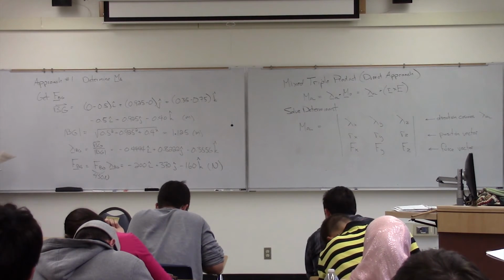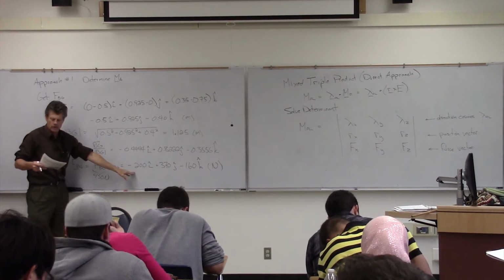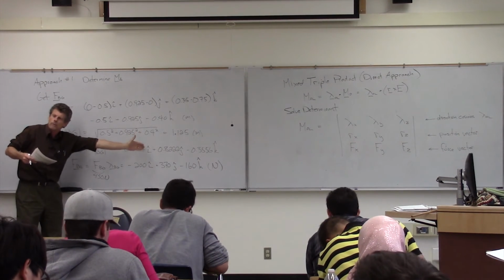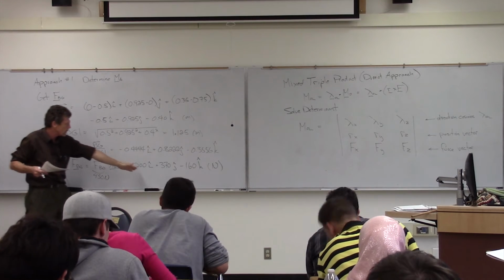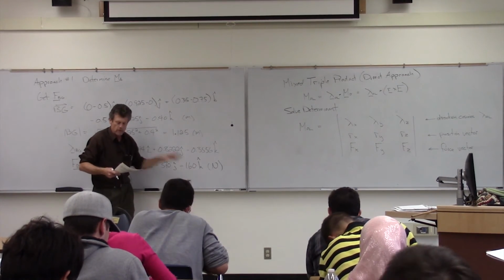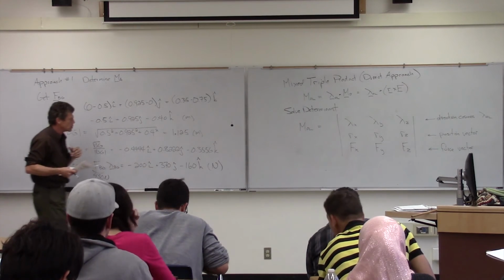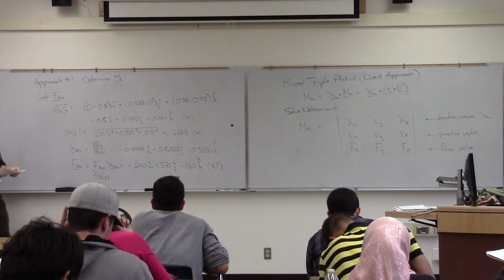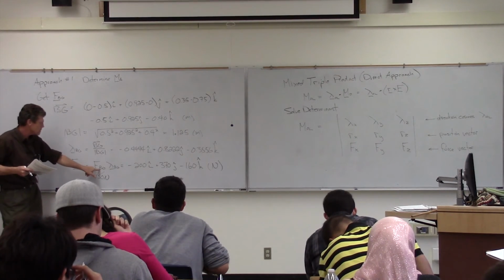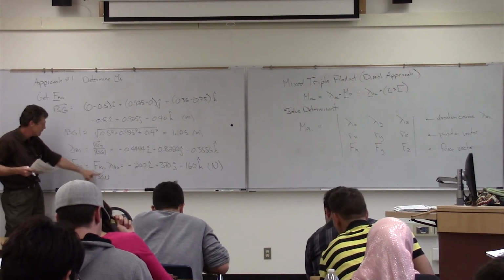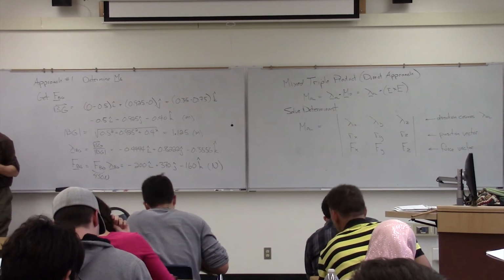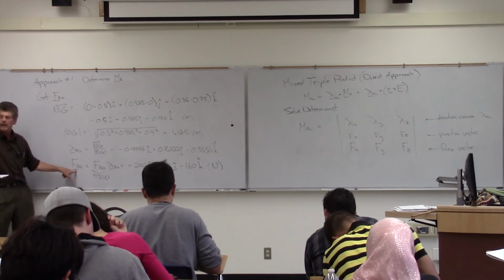And we, again, as engineers, you want to sit and think, does that make sense? Well, yeah, it should be negative, right? It's going in the opposite direction of the positive convention for x. It's going up. That's positive. And then in terms of the z direction, it's actually going back too. This is the magnitude. Remember that? Times a unit vector then, which gives us our vector in terms of FBG. So that gives us vector FBG.